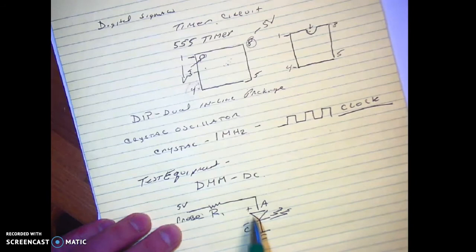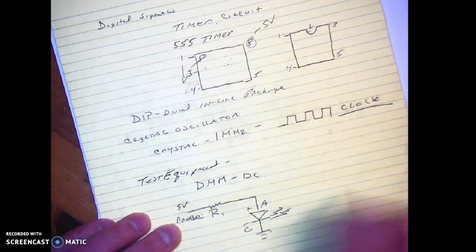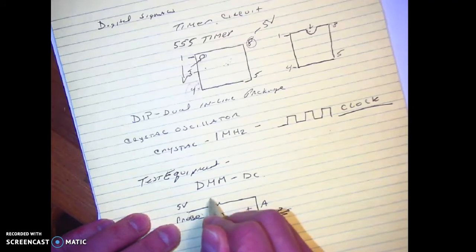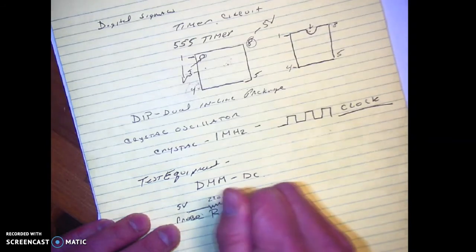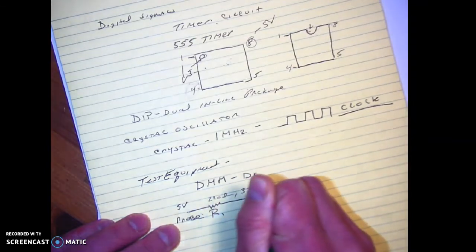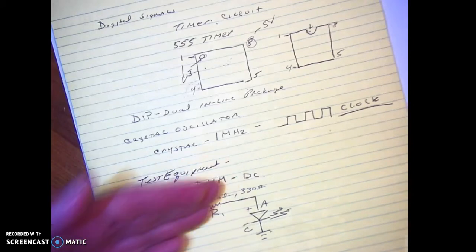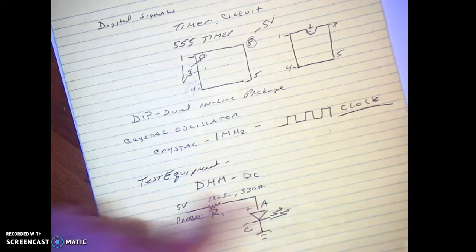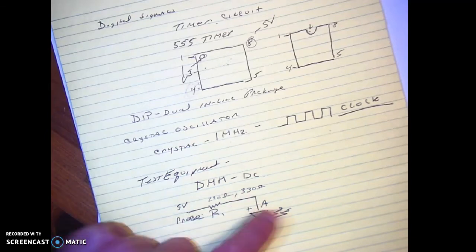And if we take this side and ground it, so you have your breadboard and you ground this side to ground, and you take this probe. Well, if this is 220 ohms, that's what we use, between 220, 330, and in some cases even 100 ohms. It depends on what you do. Probably 220 will be good, and I'll explain to you why we use these numbers instead of something else. And there's other reasons we have to use like a 1K or 10K for this, but